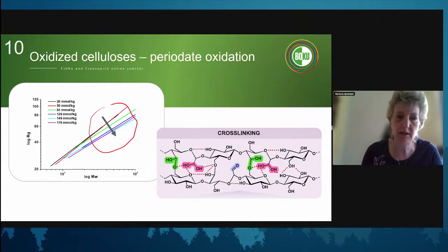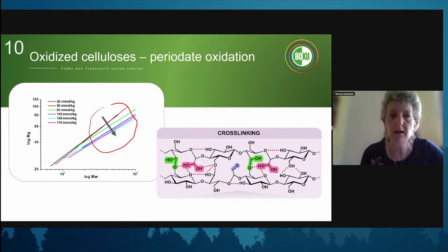The slope of the conformation plot for a typical cellulose is somewhere around 0.55 for classical paper pulps and dissolving pulps. For annual plant fibers, it goes up a little, to 0.6 something, which we usually measure for cotton and other annual plant fibers. Then if we have cross-linking, it comes down and becomes flatter.